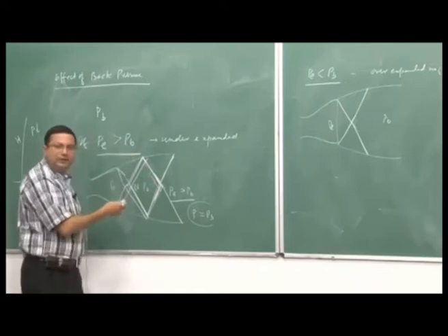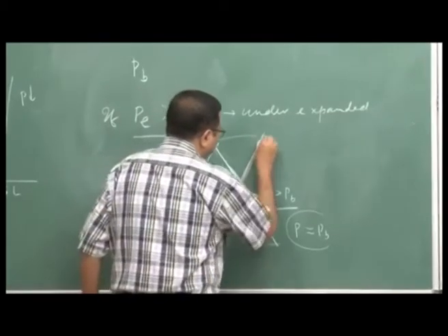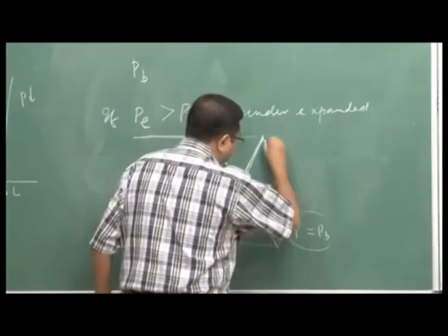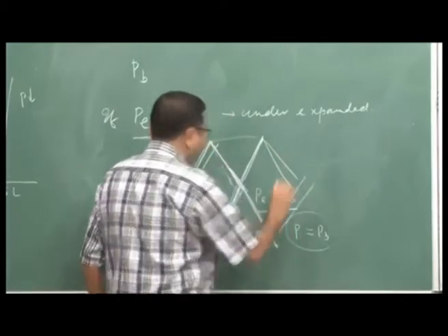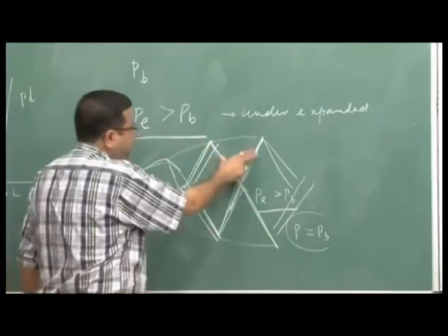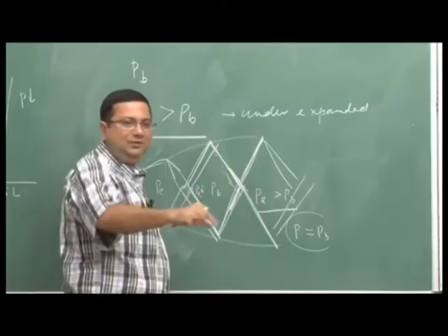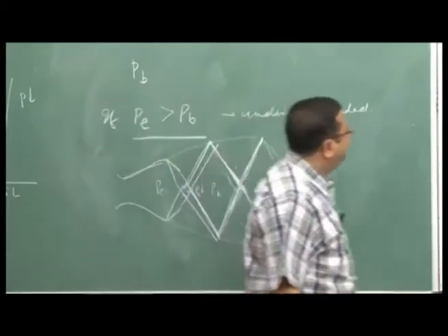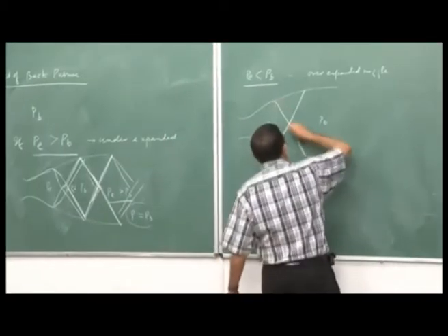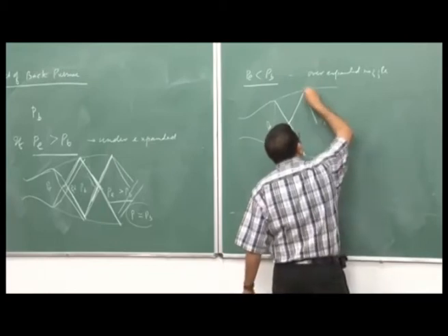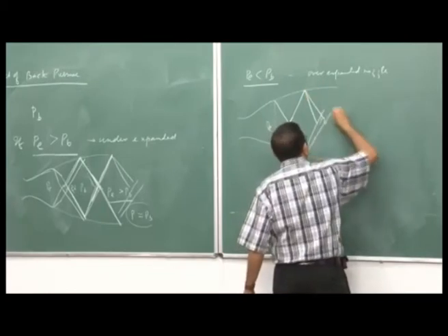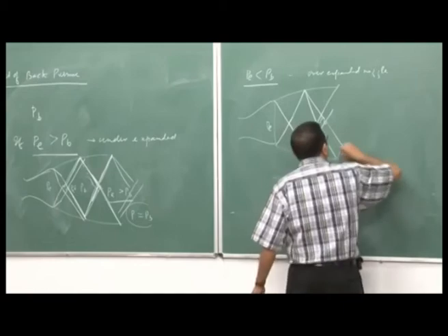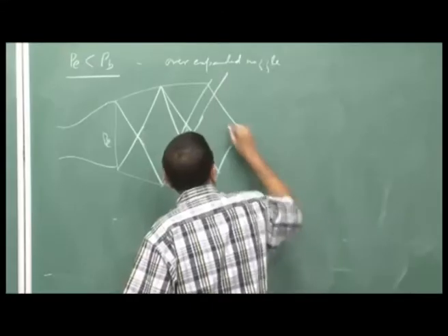From the edge it reflects as a shock wave. So, it is a shock wave, then again expansion fan, like that. Okay. These are called lambda waves, the shape of the waves is like lambda. So, here now we have a shock wave, this shock wave now reflects as an expansion fan, then the expansion fan reflects as a shock wave, like that it continues.